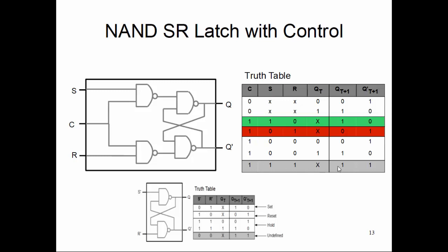Then we have one set condition, that is the green row, one reset condition, the red row, and the topmost two white rows are for the hold. So we already have the functions set, reset, hold, right? So we don't really need the bottom half of the truth table, that is the bottom white and the gray part of the rest condition. We don't need them, right?